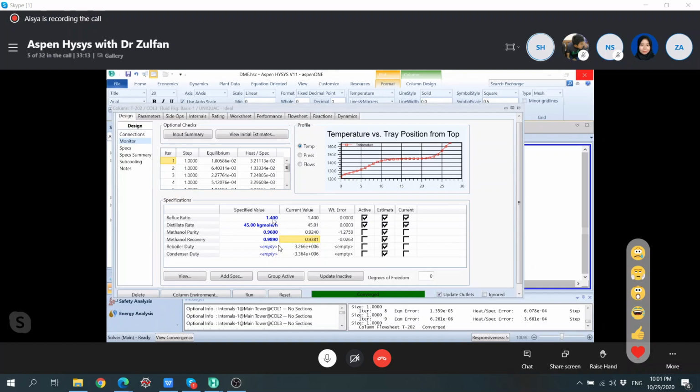The more water you put, the more you wash, the cleaner the clothes will be, right? So if we reduce the reflux ratio, it means we are reducing the washing stream into the column. So then we are left with dirtier, or less pure, methanol. Alright. So if you increase the reflux ratio, the purity will increase, but you can also see that your reboiler duty will increase as well.